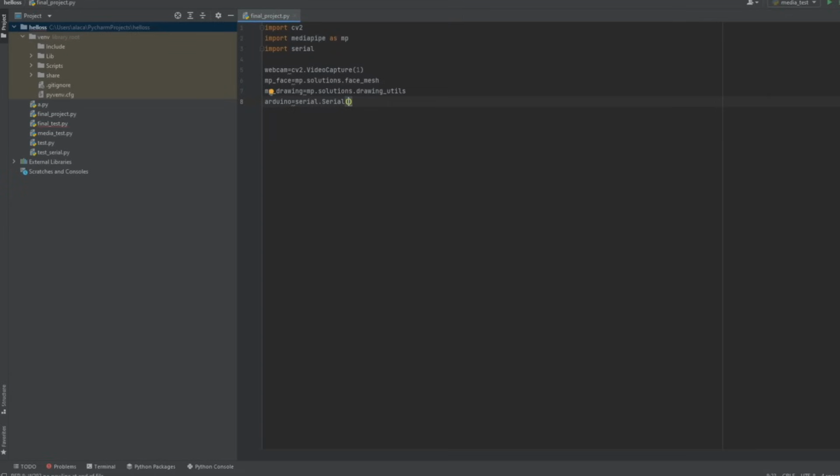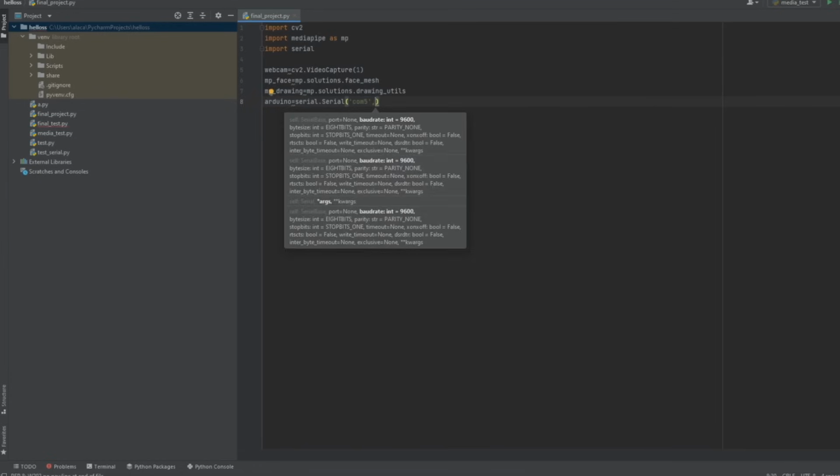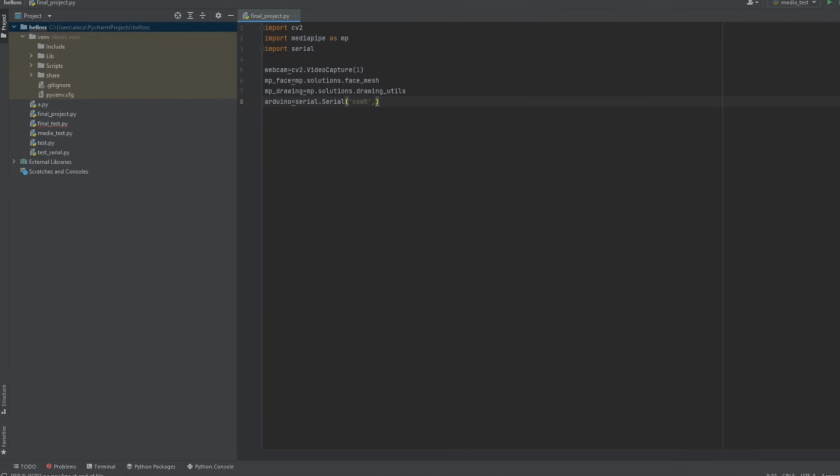If you want to define port information, we should create single quotes, and also we will write here com, and then we will define our port number. So my port number is 5, so I will define as com5, and also let's enter the second parameter. Our second parameter is baud rate speed. In general, the baud rate speed is set to 9600. For this reason, let's enter the value 9600. Yes, my dear friend, we have created our necessary modules and variables in this lesson.